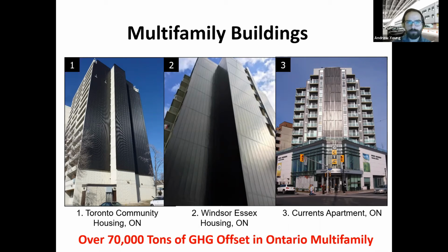For multi-family buildings, this is another area where we've seen a significant amount of interest, because a lot of the time these buildings have a makeup air unit on the roof which feeds the hallways and common areas, and that's running all the time. What we're also noticing more and more these days, especially when it comes to energy efficiency, is that building operators and owners are recladding their buildings, and that is another excellent time to look at solar air heating, because we're essentially cladding as well. So it's a great opportunity to investigate whether the solar air heating system will be suitable for the building you're considering.